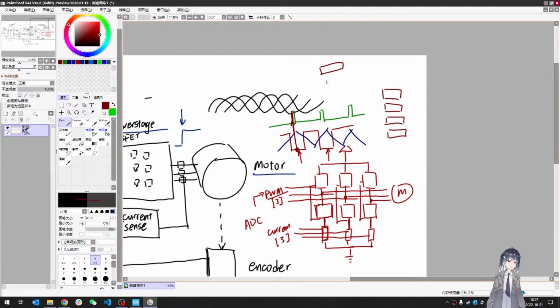And to be able to convert multiple channels, you need to use either interrupt or DMA to read out this value every time it finished conversion, and then store it into a memory location. And that is hard to configure. So basically, if we're just converting 3 channels, we're fine using the injected conversion.